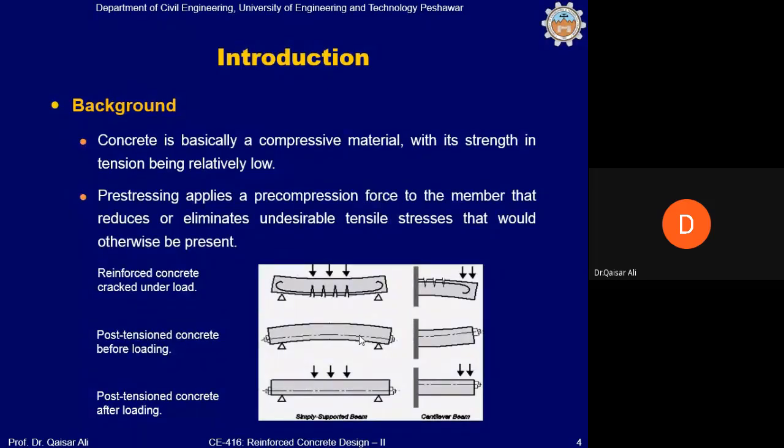Okay, so this is the principle of pre-stressing. You can look at the other situation, a cantilever beam, which is also subjected to some load, 2-point loads. Tensile stresses are produced in the upper fibers. If we can pre-compress this upper fiber before the application of the load with some mechanism, pushing this end to this end and compressing the upper part of the beam, then when this beam is loaded, the pre-compression will become zero.